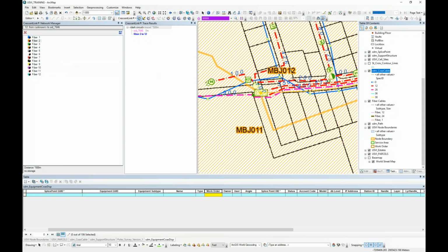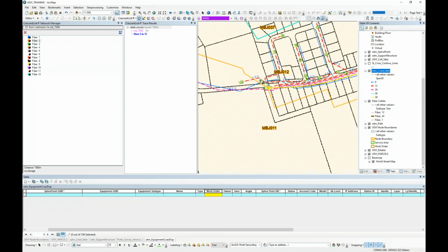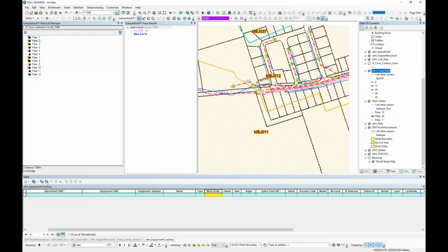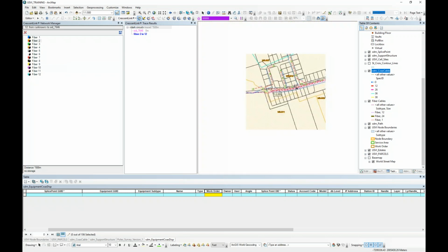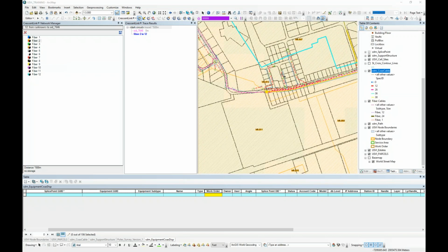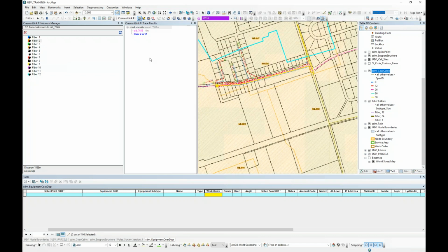When you have the larger counts, you can trace one, see the distance, and see the break in the distance. You can identify how far away it is in one fiber. If you're getting a reading of like 3,000 feet and you know what cable it's on, you know what fiber is reading at 3,000 feet, where it stops. You can select that cable and trace a distance of 3,000 feet, and it will flash and tell you where that location is, so you can go and fix that particular fiber. That's the benefit once it's all installed. It has lots of tools like that.